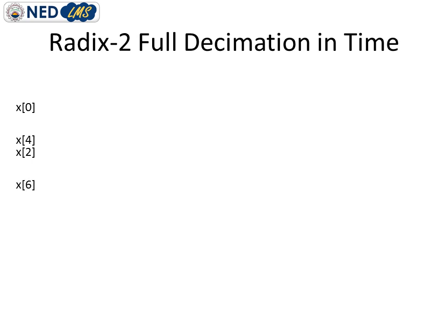As we reversed or shuffled the input samples at the input side, we will get the frequency output in ascending order, that whatever the output will be, it will follow x of 0, x of 1, x of 2, x of 3, and we do not need to shuffle the output values. But if we do not shuffle at this stage, then we will get the output in shuffled form. So it's better to do it here for easiness.